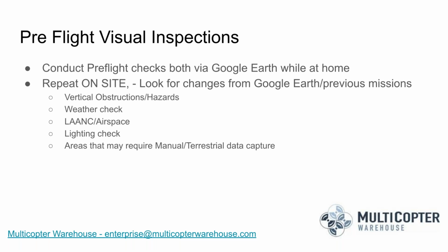Okay. In a pinch, can a Mavic 2 Enterprise Dual work for vegetation? Well, if you're talking about thermal, it's going to provide a certain level of information, but it's not going to provide multispectral information. One thing that is very useful when you're using just a thermal camera in agriculture is water runoff. It's very valuable for that to see where things are dry versus where they are wet, because that's going to have a temperature variance.